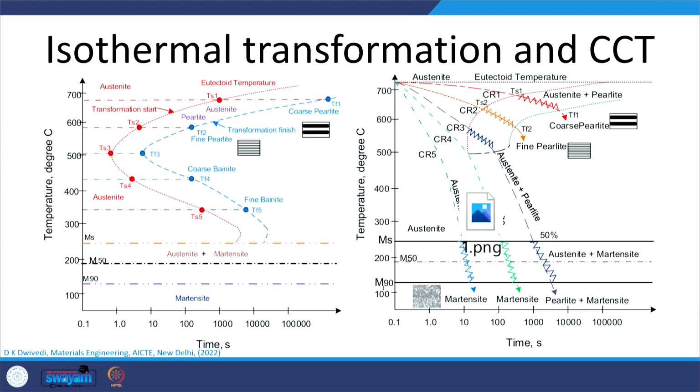But during the welding, the cooling is continuous, it is not fixed. So, the zones next to the fusion boundary will be cooled very fast, cooling rapidly, but the zones which are away will cool slowly, and further away more slowly. So, the cooling rate experienced by the steel during the welding changes with the location. And if the steel is hardenable, then depending upon the cooling rate it experiences, it will form different phases.